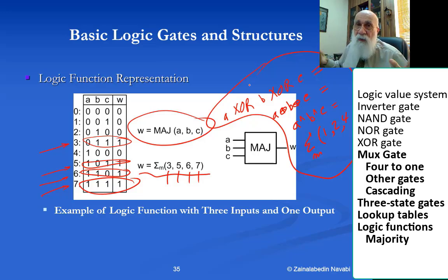If you go beyond just NAND gate and NOR gate, you go into a majority gate using CMOS logic with PMOS pull-up and NMOS pull-down structures, that is called a complex gate. Therefore a multiplexer, an XOR, a majority function, all of these can be implemented using a complex gate structure.